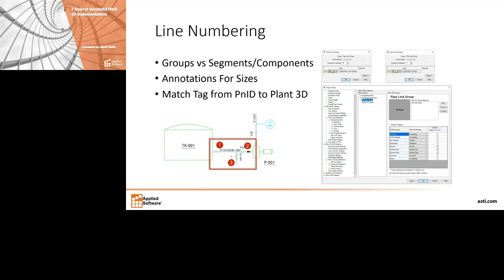Now, when people use the software, one of the most common issues and mistakes we see made is that the P3 line group class over here at the top right, most of the time they'll add in the size, the spec, the installation and heat tracing that they want to see on the drawing file. And so that's the reason that is inappropriate, is that's a lot more properties that it's going to check and compare against for consistency. And so, for example, we could have 4-inch CS150 NH1001. The program would also let us put in 3-inch CS150 NH1001. Well, those are really duplicate values because we want only one line number 1001.